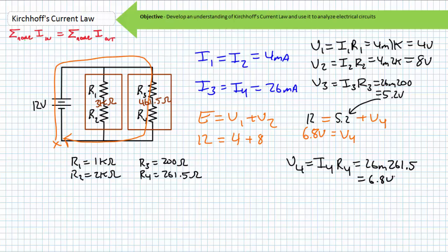The point of this diversion is this: don't solve for stuff you don't have to. You don't need to solve for the current through elements hooked in series because current through elements hooked in series is the same. You don't need to solve for voltage across elements hooked in parallel because voltage across elements hooked in parallel is the same. What goes up must come down regardless of which loop you travel, and what goes in must come out regardless of which node you look at.